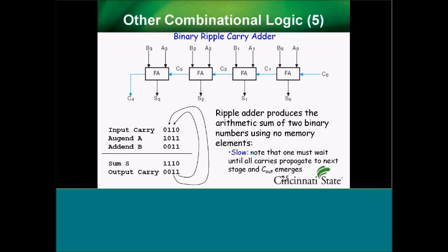So that entire chip would be 2 4-bit words, A0 through A3, B0 through B3. Then you have all those carries, C1 through C3, all that's internal carry. The C0 is external, and C4 is carry in and carry out. And then you have your 4 sums. So this becomes just a chip. It's a 4-bit adder chip.